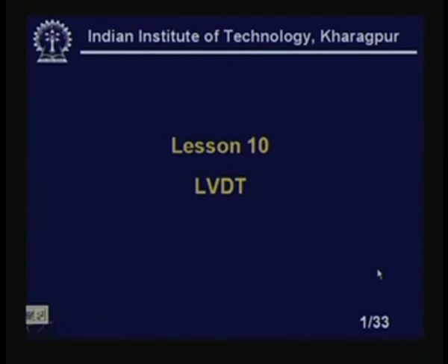In this lesson, we will study LVDT. The full form of LVDT is the linear variable differential transformer. It is basically an inductive or inductance based sensor, and primarily it is used for the measurement of displacement. However, I can use it for measurement of pressure and other process parameters also.